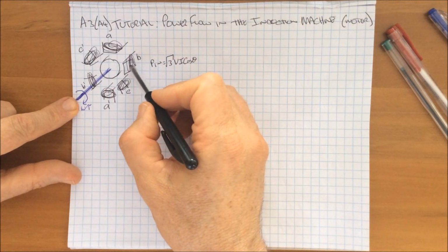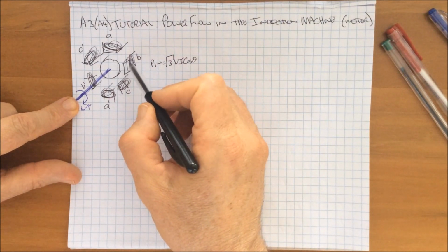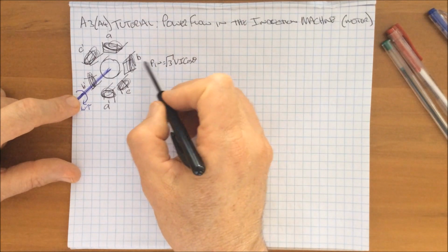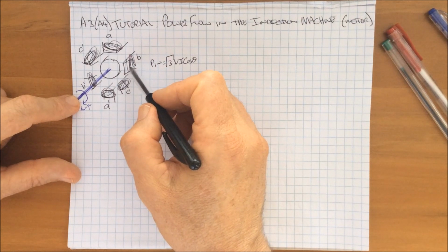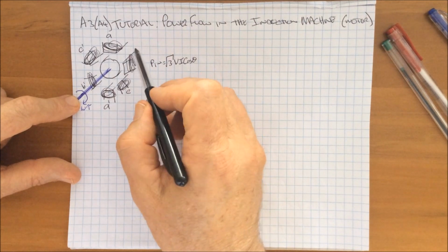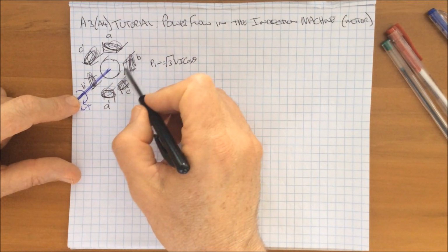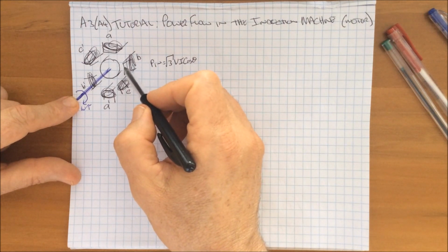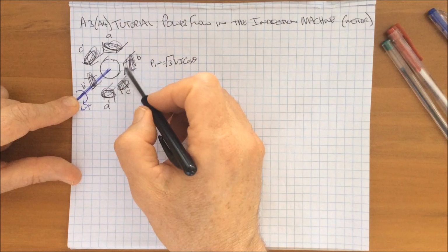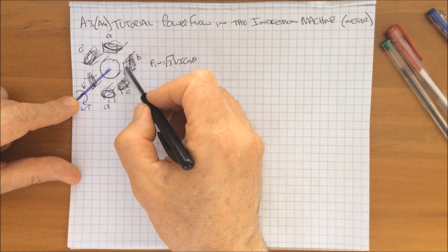As the power goes through here, we're going to be losing it. We're going to be putting this electrical power into these wires. These wires have resistance, therefore there will be an I²R loss there. The core here is made of laminated material, so therefore there will be eddy currents and various things like that, and hysteresis losses and all of those sorts of things going on.